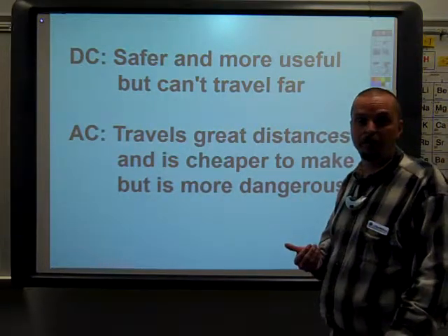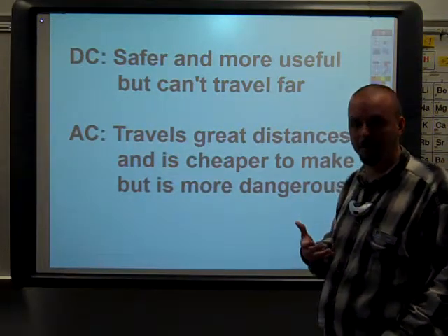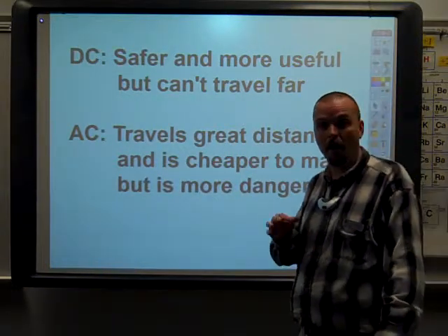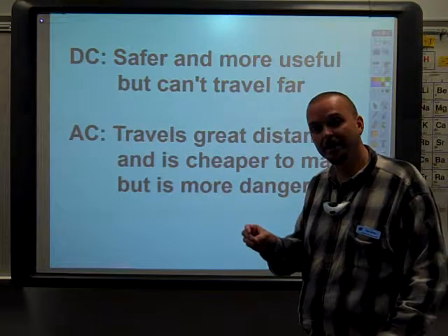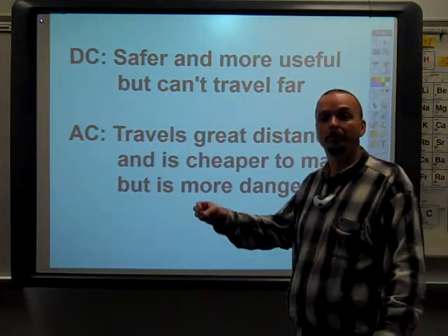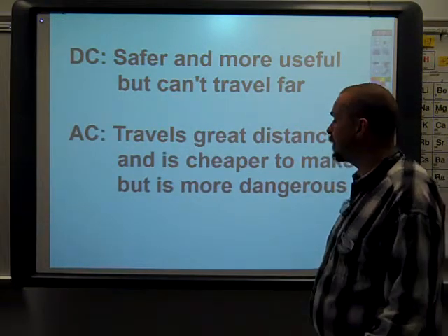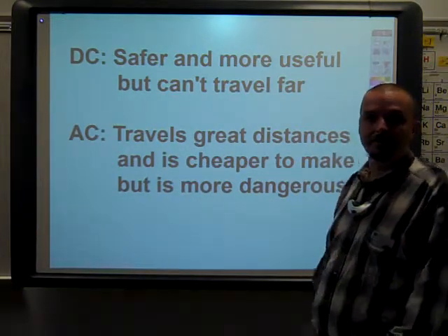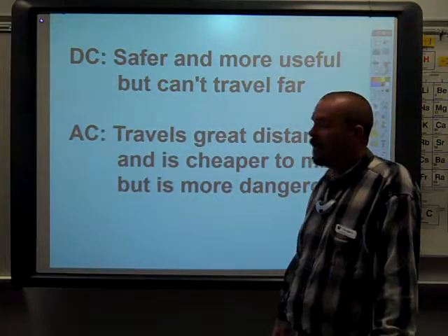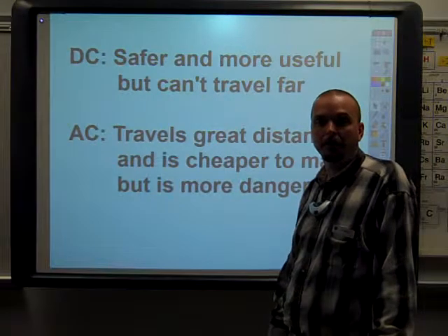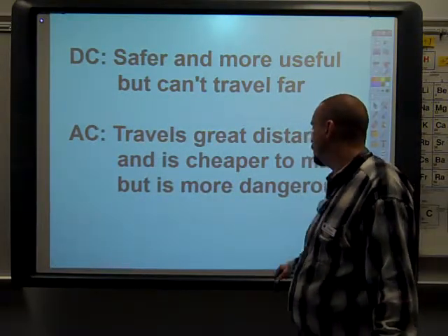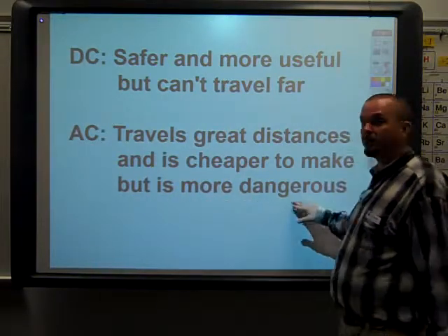If you've ever been shocked with alternating current, it feels like a buzzing sensation. The reason it feels like that buzzing sensation is because the current is being turned on and off. Your muscles are contracting, relaxing, over and over and over again, and that is that buzz, that is that vibration that you feel. In our electrical outlets in the United States, it turns on and off 120 times every second. Now imagine if that were to get to your heart muscle, making your heart muscle literally beat 120 times a second, tears it apart. And that is really what makes it so dangerous.